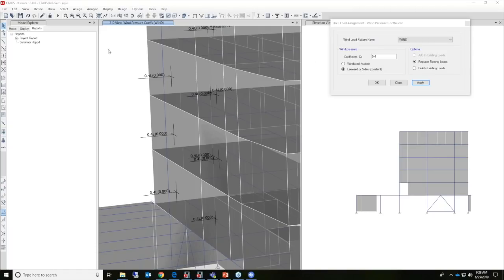When defining a semi-rigid diaphragm, is the program able to calculate the in-plane stiffness characteristics of the diaphragm based on materials, or do those values need to be calculated outside and entered by the user? Yeah, the program is able to calculate the in-plane stiffness of the semi-rigid diaphragm based on the thicknesses and the materials that comprise those floors.